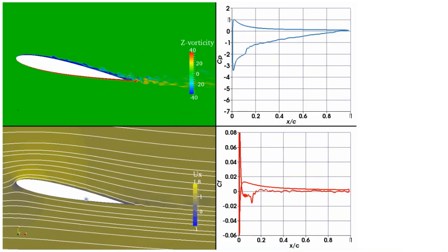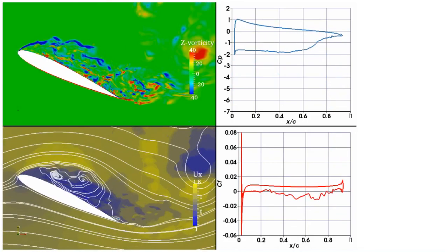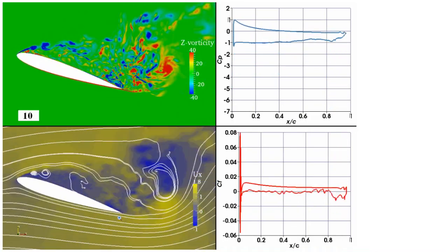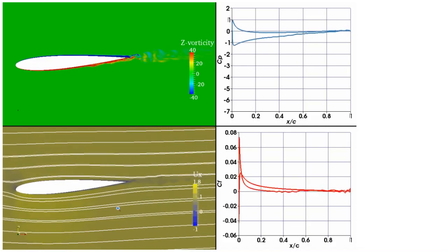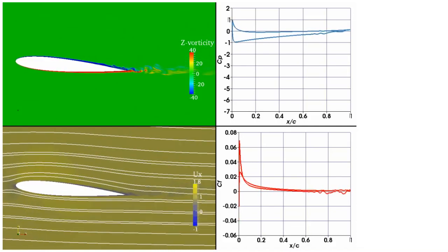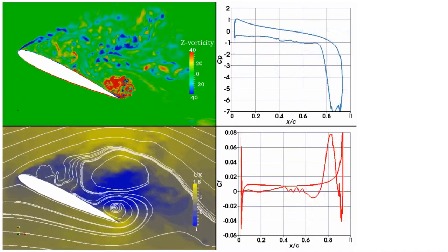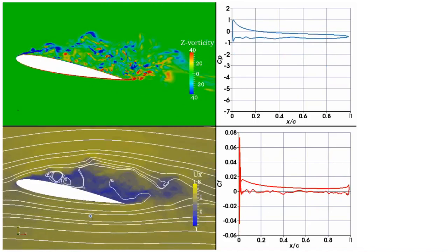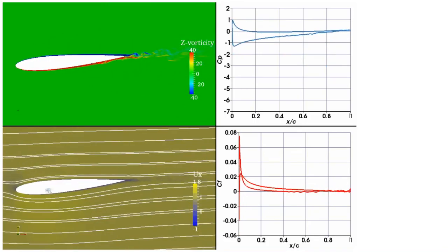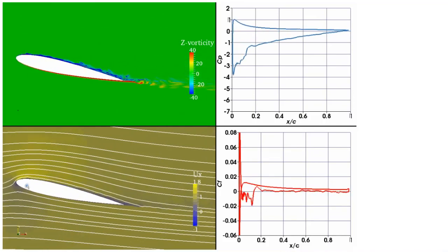So when the angle of attack is close to zero, you have little turbulence. That's why you have a lower value for the drag of the airfoil. And here you can see how the streamlines of the flow are modified when the angle of attack of the airfoil changes.